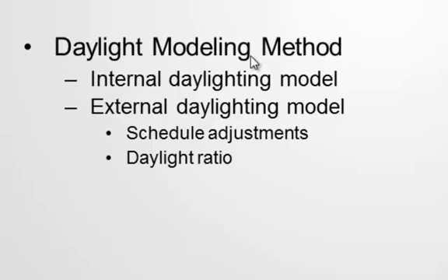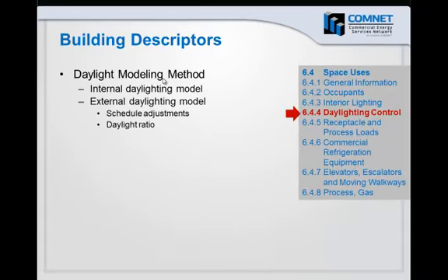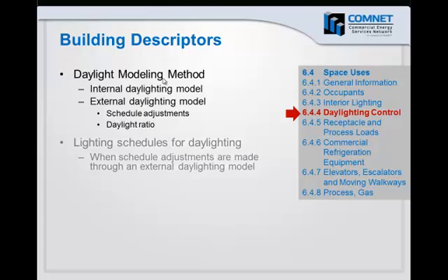a more detailed model where the sky is divided into patches, and there's essentially a daylight factor for each patch of the sky, and they're all added up for the daylighted space. And there's also language that allows other daylighting modeling methods to be used if they're supported by the simulator. The second building descriptor under daylighting that I'll talk about are the daylighting schedules.